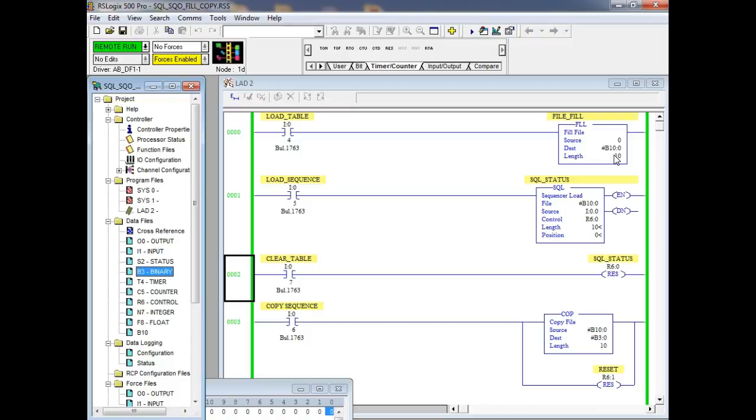Which is a pretty neat aspect of it. You can understand how many lines this would take out of a program. So if I wanted to do all these different combinations, then we would have a lot of lines, right? You understand? But a sequencer gives us the ability to replace it. If we got something that runs in a sequence, then this would be the guy to use. Because we could replace 256 runs with one sequence. Pretty neat. And you could parallel these things, by the way, and use two different tables. But we could actually output 32 outputs at the same time.